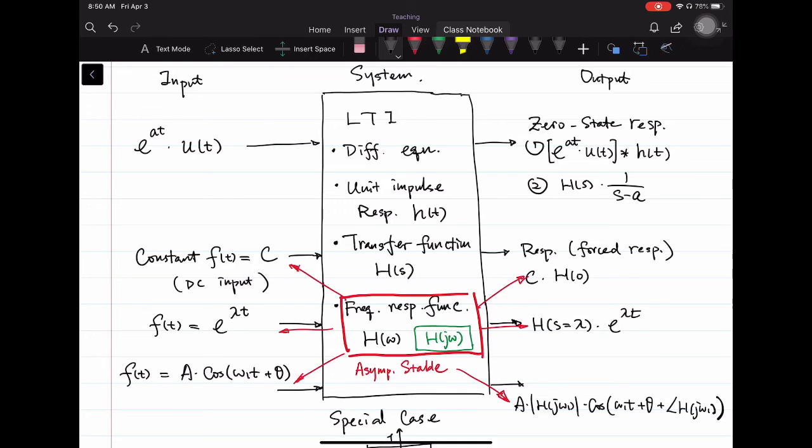And for the two transforms, as I mentioned, for the Fourier transform, its advantage is in the fact that this omega in this j omega has a physical meaning. It actually represents the frequency component in the signal. But it has a lot of restrictions as well, as we discussed.